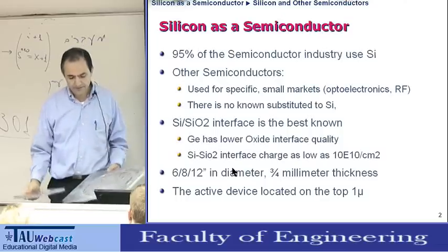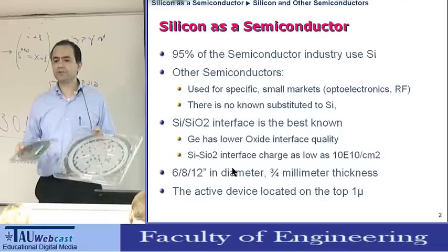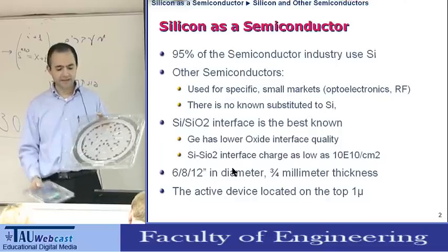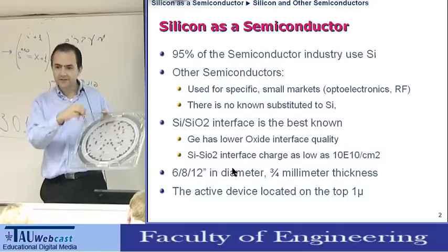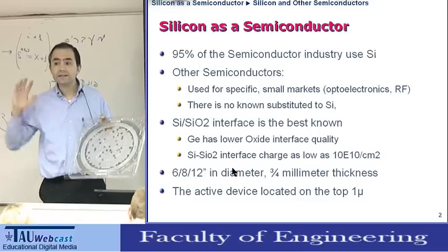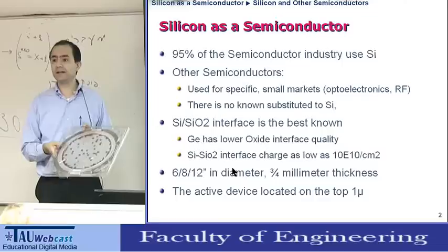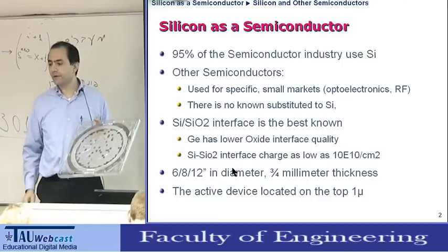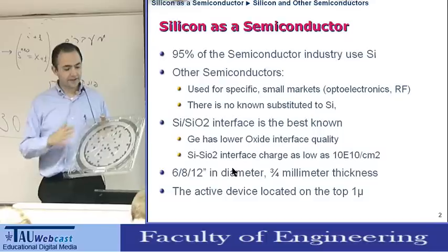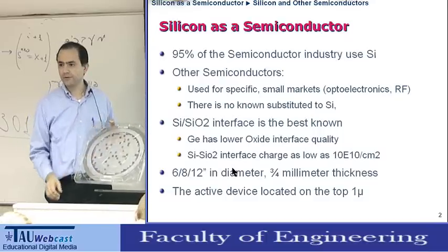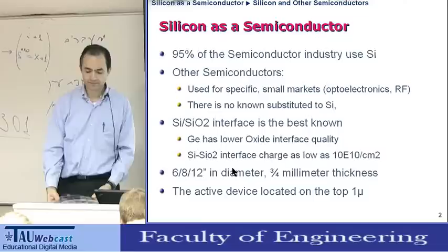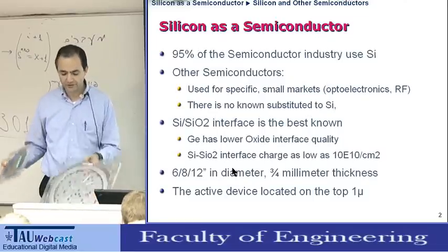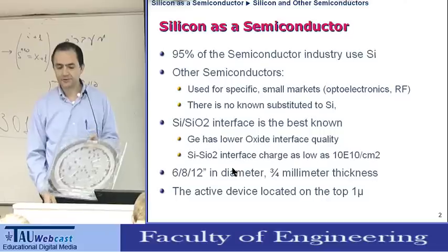Now, there's one thing which is not being done on all the wafer at once. What operation is being done very selectively? Lithography. And why is that? For lithography, very few processes can use one mask for all the wafer. Very, very few. Actually, I know of such processes in 8-inch. I don't know of any such processes at 12-inch.